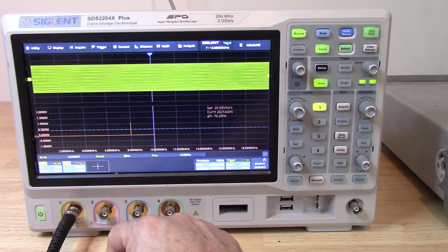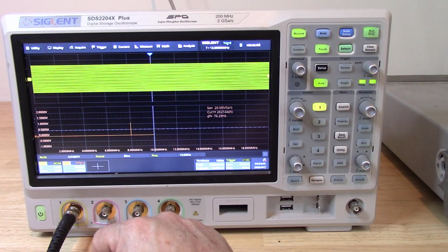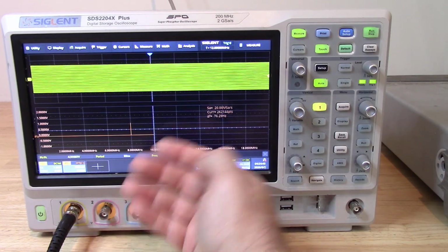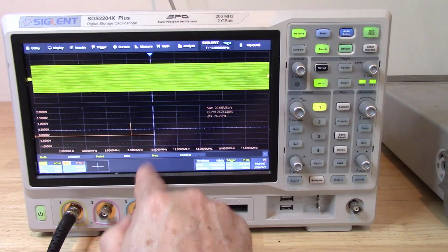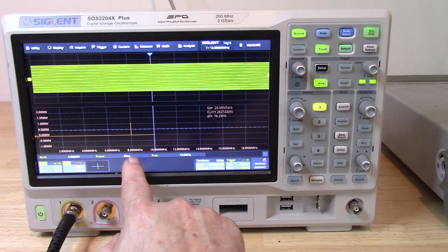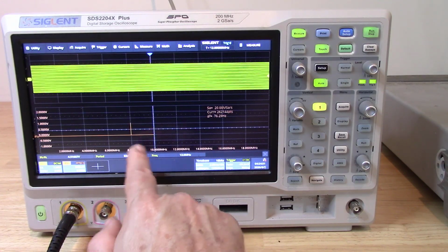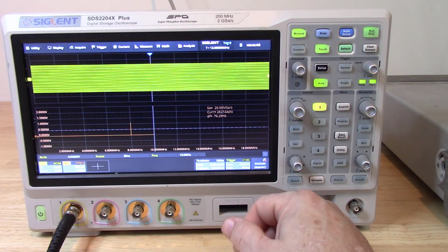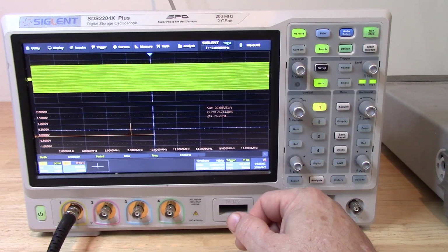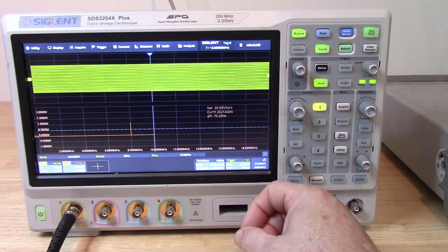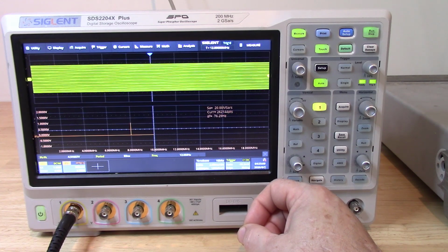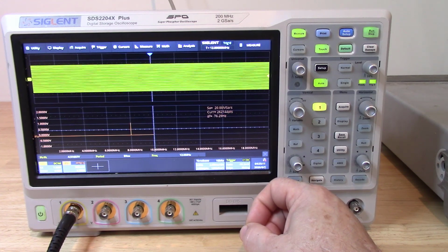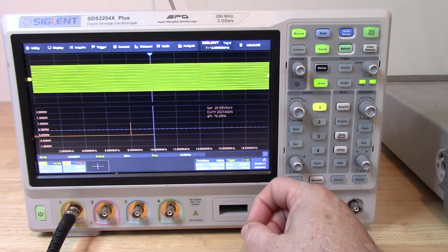I'm at 12 megahertz, it has exceeded the Nyquist frequency by 2 megahertz, and so it folds back from 10 megahertz by 2 megahertz, and you end up with all the energy at 8 megahertz. It's very difficult to see that as a standing wave. I can tell you that the 8 megahertz is definitely present in your digital data. It is not present in the input signal.